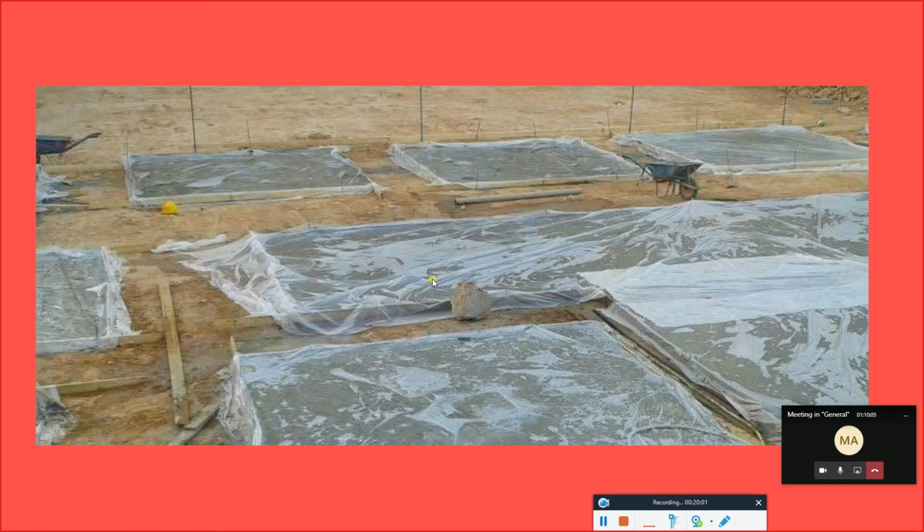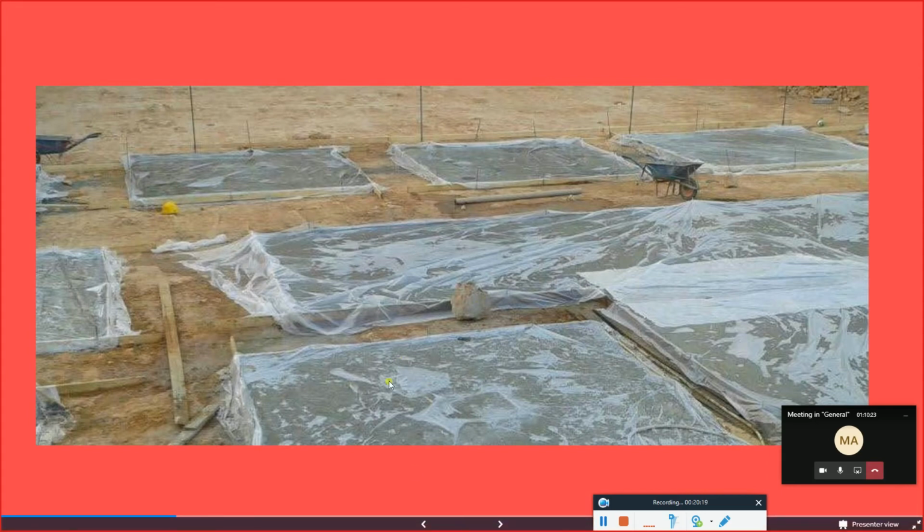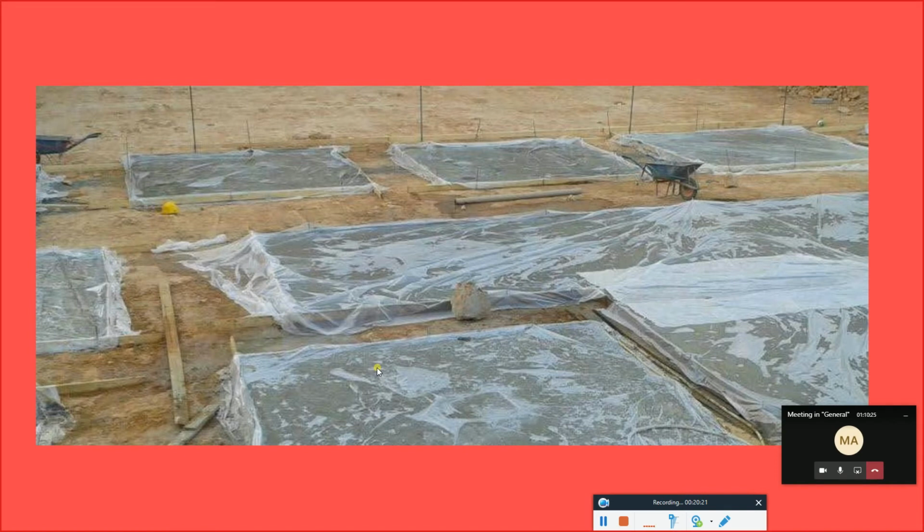So in order not to let the water evaporate from those places, we can put either cloth, like fabric, or we can put the sheet as well. So if it's beneath, then it's waterproofing. If it's above, then it can be used for curing purposes.